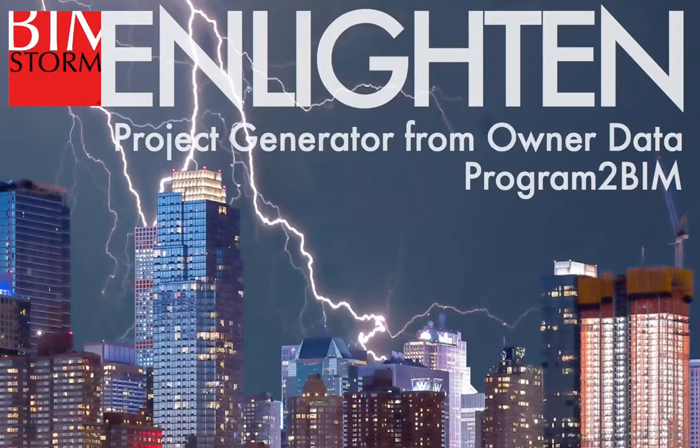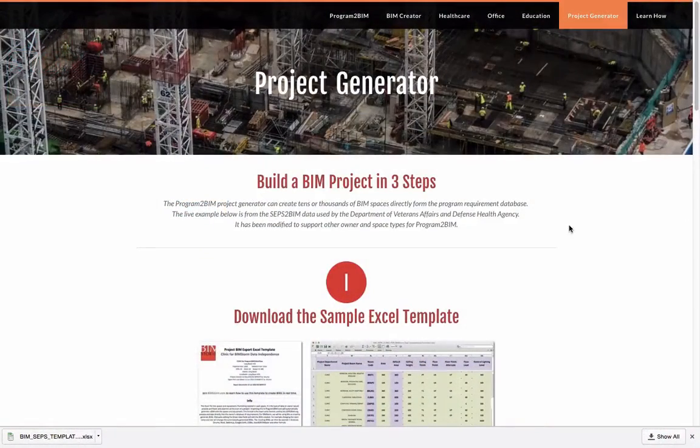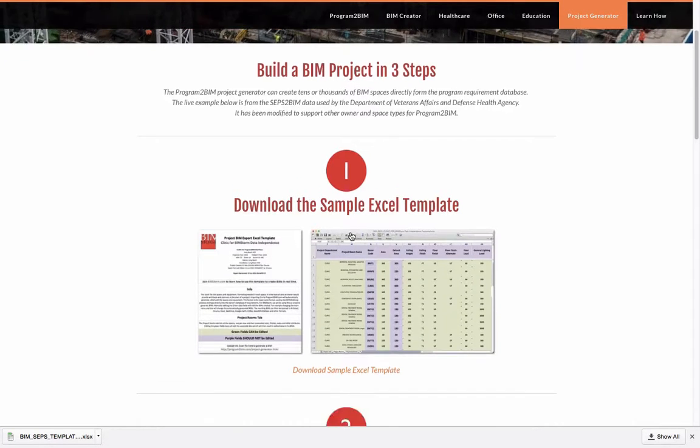In this session, we'll talk about Project Generator using Program2BIM. On the Program2BIM website, under the Project Generator tab, it outlines the 3 steps that are needed. Step 1, download a sample Excel template. This is typical of the Excel templates used by the Department of Veterans Affairs for healthcare facility planning, but we can use it for other types of projects as well.